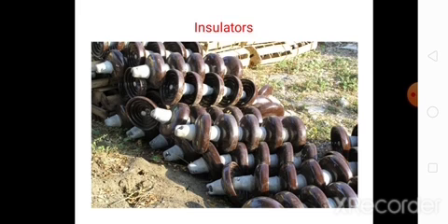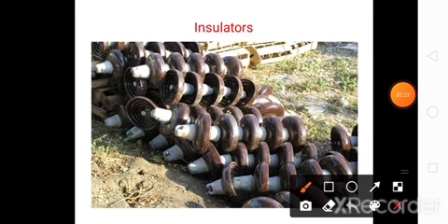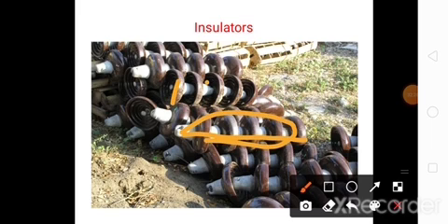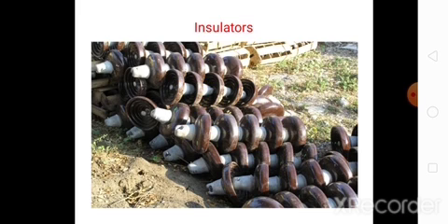These are the suspension type or strain type insulators. Each disc is rated at approximately 11 to 16 kV. So if there are 5 discs, that is 11 kV into 5, approximately 55 kV, which suits a 66 kV line.